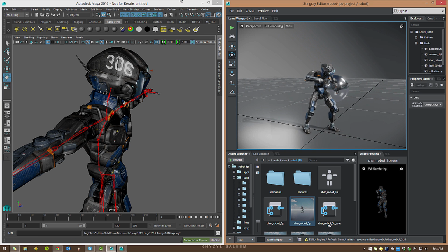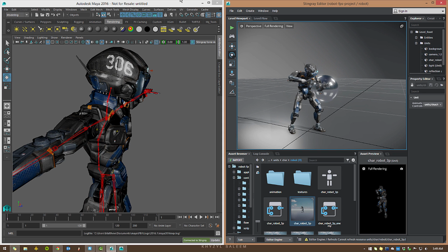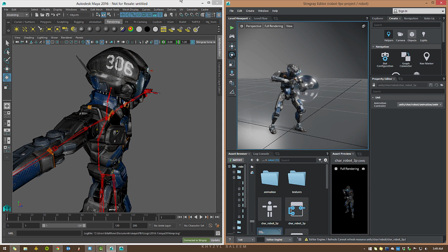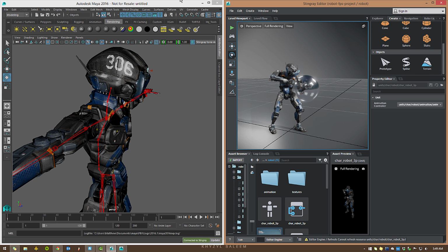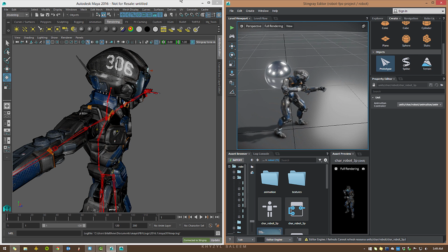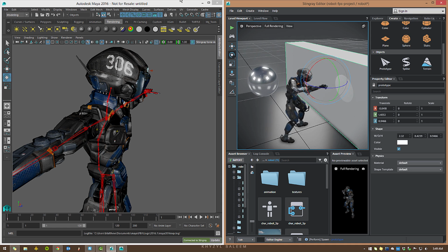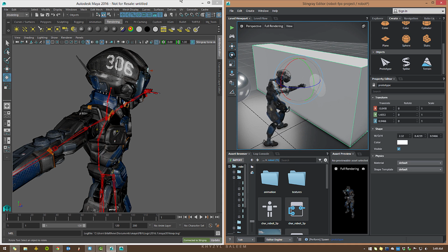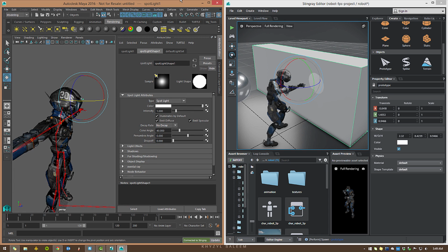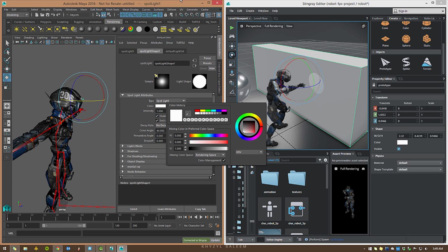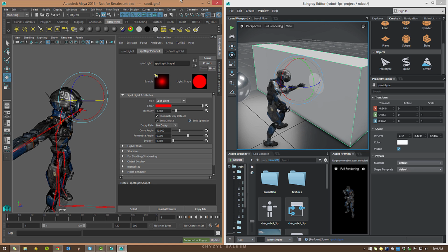all right, now let's go ahead and add a surface that light can shine on. So we'll go over to Objects, and we'll just create a prototype surface here. And there's our light, just like that. Pretty neat. So now I could maybe change the color of that light inside of Maya. Let's make it red. Change the intensity. Update. And there you have it. The light is now red.